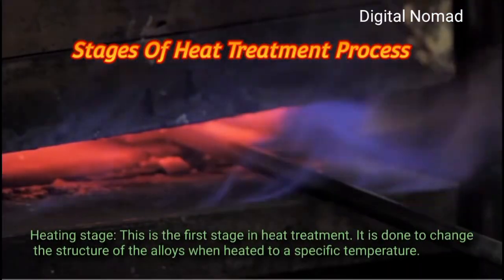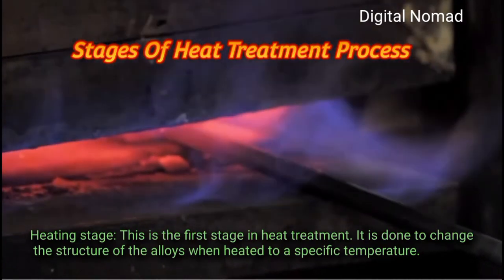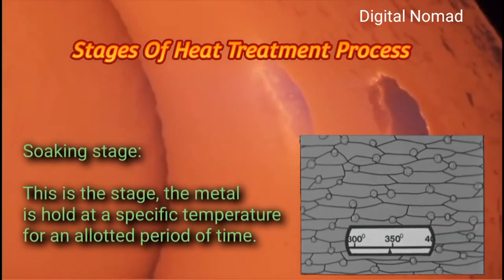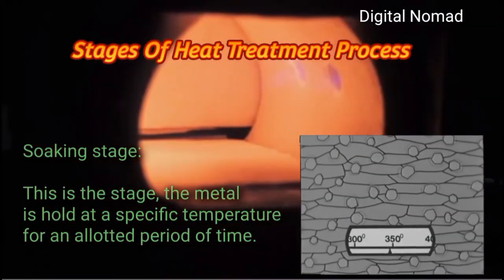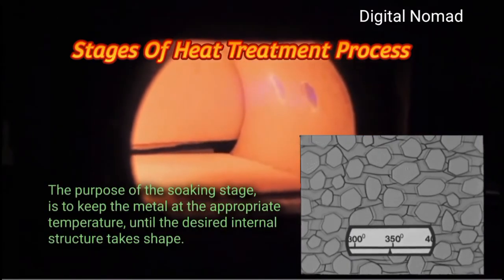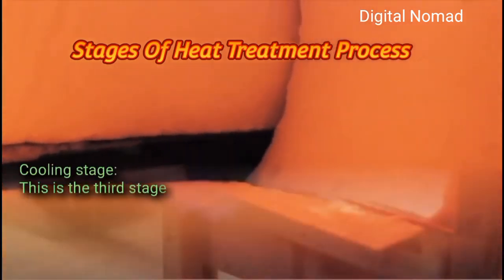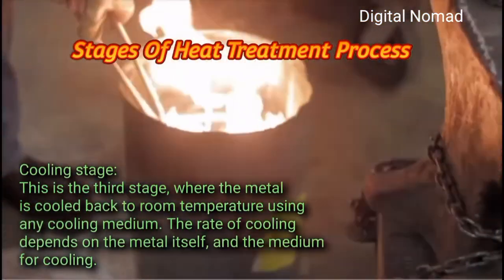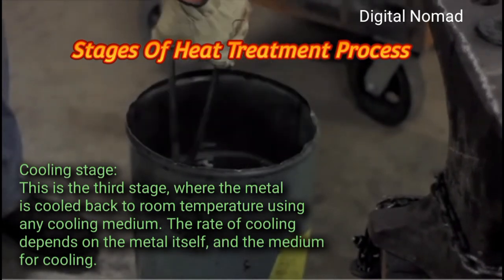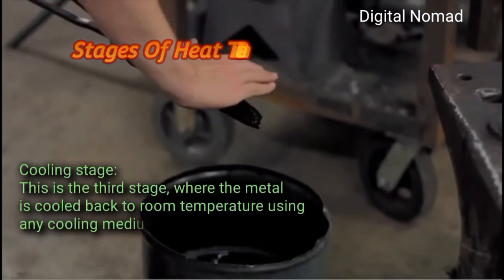Heating stage. This is the first stage in heat treatment. It is done to change the structure of the alloys when heated to a specific temperature. Soaking stage. This is the stage where the metal is held at a specific temperature for an allotted period of time. The purpose of the soaking stage is to keep the metal at the appropriate temperature until the desired internal structure takes shape. Cooling stage. This is the third stage, where the metal is cooled back to room temperature using any cooling medium. The rate of cooling depends on the metal itself and the medium for cooling.